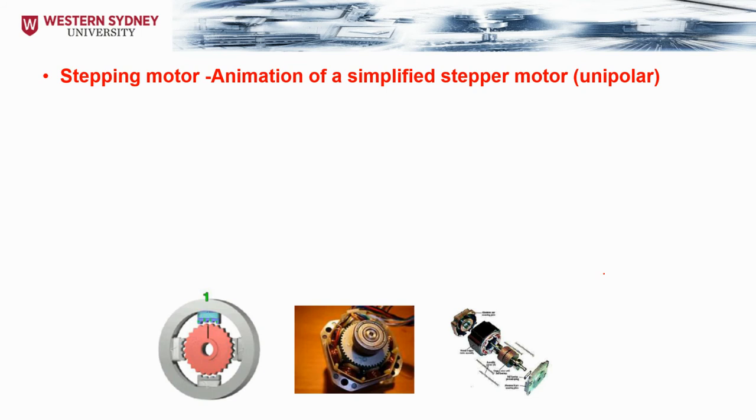Once again, the stepper motor, as we explained earlier, is going to have a certain number of steps to be rotated. This one, for example, has only 4. That means for a full revolution, where this line goes back to the same position again, we need to use 4 steps. It's going to be nice to read about that before you come to this one. We're always going to have an angle between the steps. For example, by doubling the number of the steps, the angle between the steps is going to be 45 degrees, while the angle between the steps in the previous one is going to be 90 degrees.